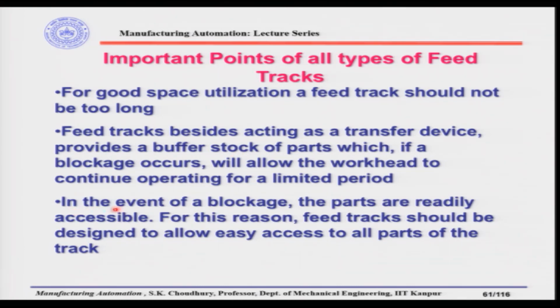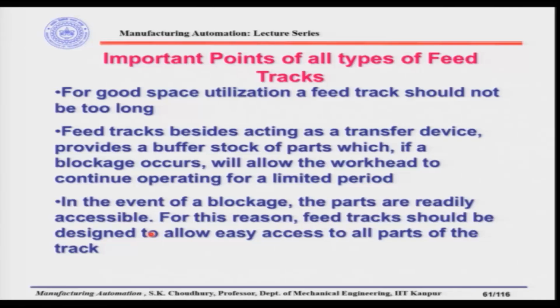The third point is that in the event of a blockage, the parts should be readily accessible. I showed in the line diagram in the beginning that the parts have to be accessed easily. Therefore, it is normally either open, or you can easily remove the lid, so that you can access the parts. For this reason, feed tracks should be designed to allow easy access to all parts of the track, either by keeping it open from some side, or so that you can easily remove the lid.